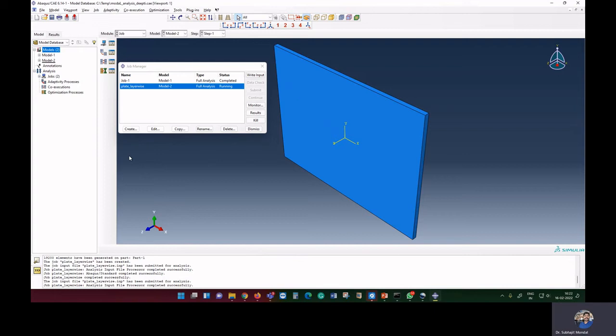Next, our job is to change the angle of ply, and we need to see whether our result is changing or not, whether the analysis we are doing here is correct or not. So what we did, we initially modeled using a 3D solid element, and then we defined the property as layer-wise, and we have selected 4 layers.